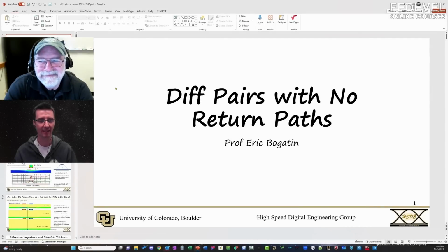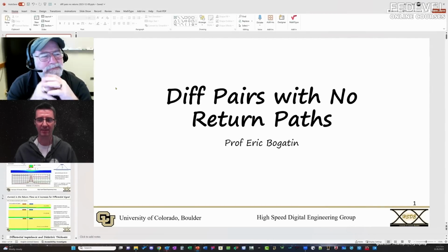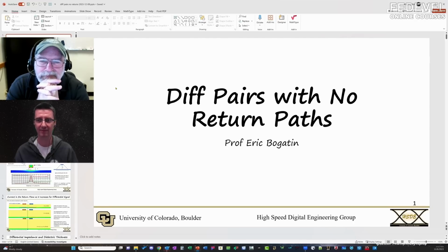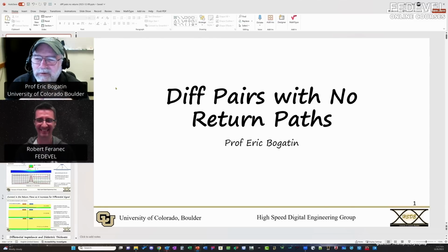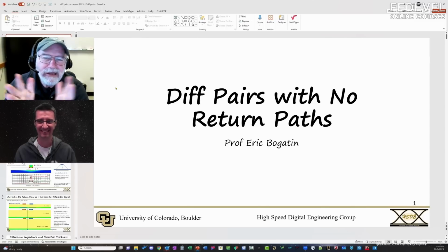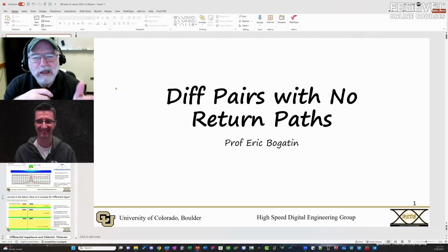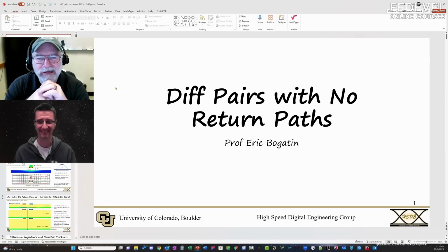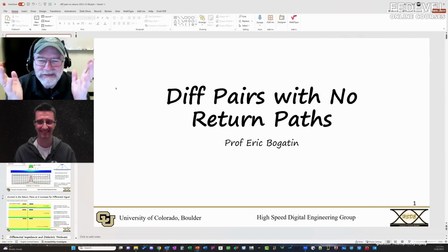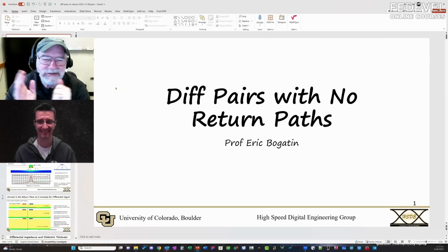Many people ask me, I have differential pairs, why would I need ground? Or do I really need ground? And what do you think, Eric? I get exactly the same question. When I talk to engineers that are just learning about differential pairs, they always tell me, wait, I hear all the time that one line in a differential pair carries the return current of the other line. Why do I need a ground plane if I've got a differential pair? Doesn't the other line carry the return current? There's not supposed to be any current in the plane, so why do I need a plane in there?